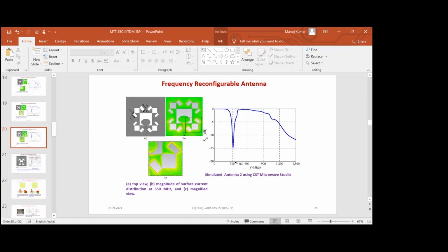When you are connecting these components to any antenna circuitry, any RF circuitry, don't use solder. Don't use electric soldering. There is surface mounting paste. Use that paste and connect the components. If you use soldering at any frequency, lower or higher, you are incorporating additional losses, because solder is a lossy material. So take care of that.